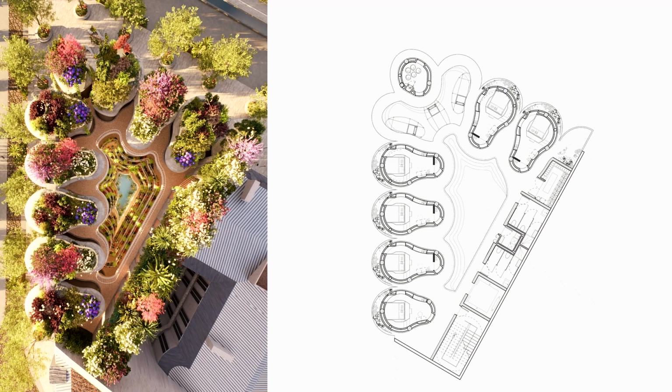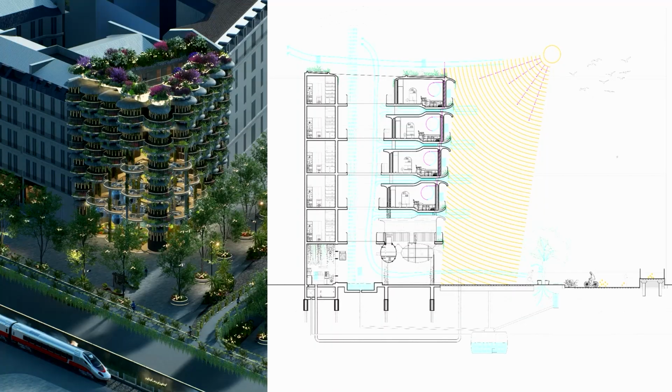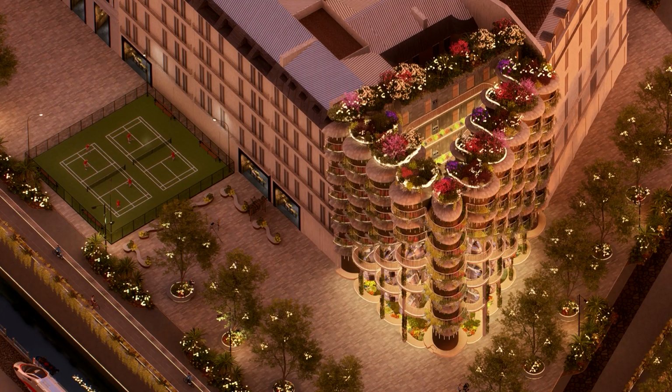Seeing the wind in context helps shape the building as a scaffolding for living units, rather than just one monolithic enclosure. In section, the tower draws wind through gaps between each of the enclosed permanent living units. The units are shaped to compress and then expand the wind to accelerate it via the Venturi effect. And then a central core draws air upward and amplifies airflow through the stack effect. This led to a climate-resilient tower shaped to harness the wind conditions of the site and to maximize passive cooling.